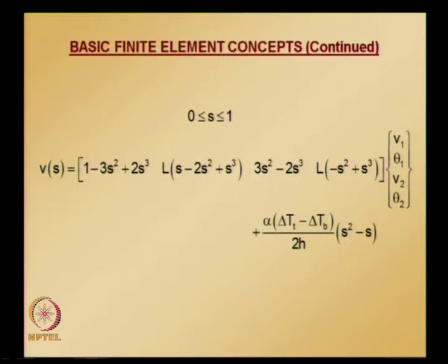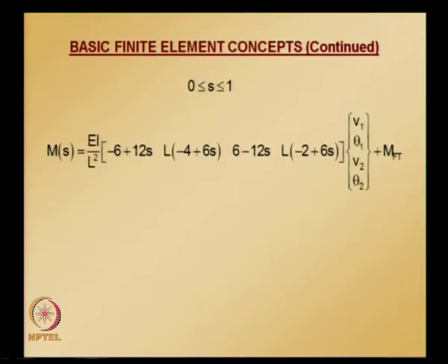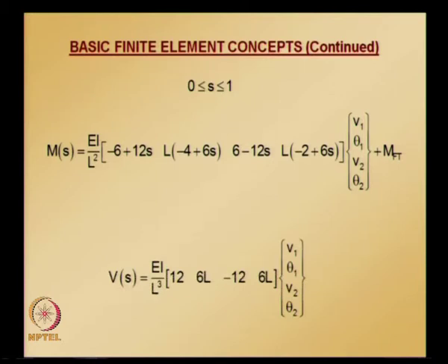And now moments, similarly, have a correction term in addition to the finite element interpolated values, and please note that there is no shear because of these thermal stresses and fixed end condition, so there is no correction term for shear force.